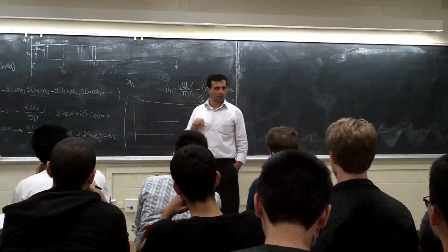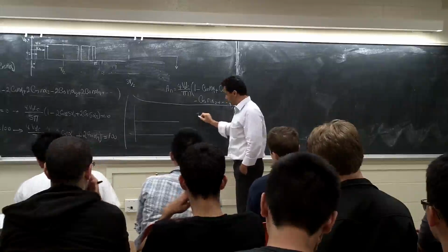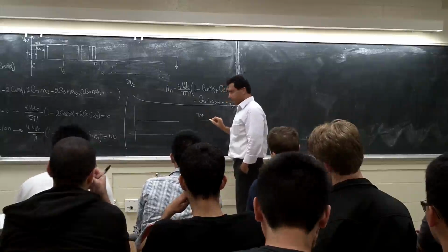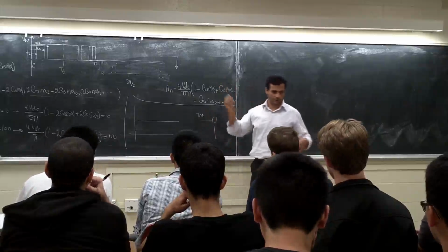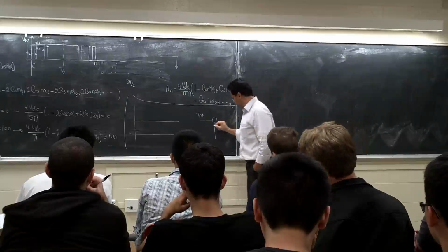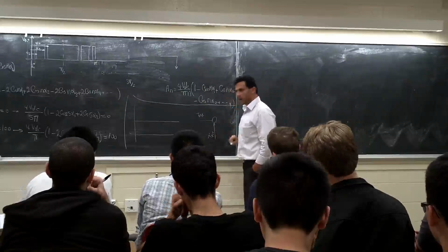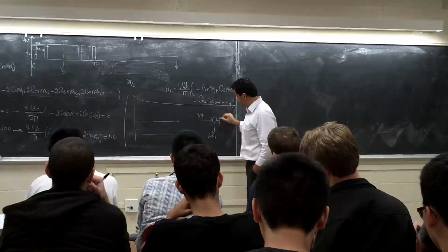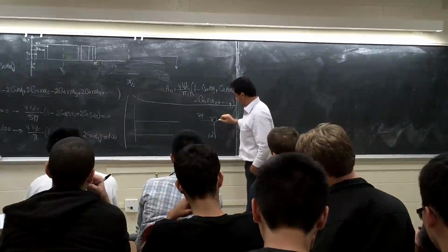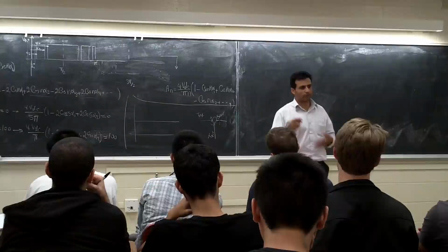So what we do with the control system is like this. I have a reference value, for example T reference. And I go measure my actual temperature. I put the sensor somewhere and measure the temperature of this room. This is the T actual. The difference between these two is going to give me the error.